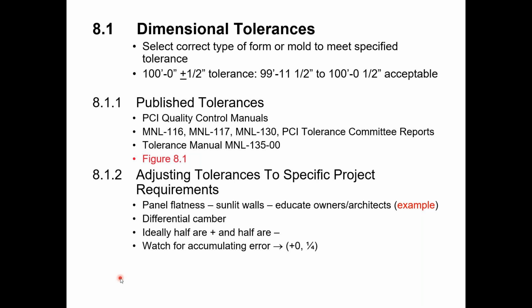If you're casting a wall panel on a wooden deck with wooden side forms that have to be built every time, you're introducing the opportunity for user error. Sometimes the nature of the project governs what you have to do, and you don't have a lot of choice, but you at least need to understand that with certain types of form work, meeting these tolerances may be more difficult. So be prepared for that.